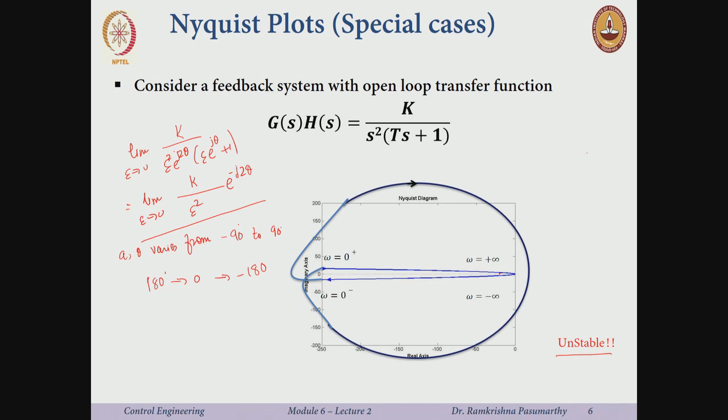So, this is how the Nyquist plot looks like. Now, can we infer stability of the closed loop system? So, again we look at the number of encirclements, right. What I am interested in here is again the point minus 1 plus j 0, and I see here that the plot encircles the point minus 1 plus j 0, this is our point of interest. So, if I look at it, well, it actually encircles it 2 times. So, the total number of encirclements is 2. Now, how many open loop poles are in the right half plane? Well, the answer is P equal to 0, and if the system were to be stable, what we need is N equal to 0. Now, N is not equal to 0, N instead is 2,